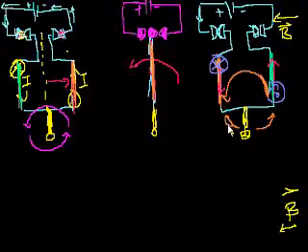I mean, most electric... Well, there's another way you could have done it. You didn't have to use the commutator. One methodology you could have used is you could have had the magnetic field going until you get to this point, and then you turn off the magnetic field, right? And maybe you wait for this situation to go all the way 180 degrees, and then you turn the magnetic field back on again, right? That's one possibility, but that's maybe not as efficient because half of the cycle you're not powering it. Or maybe you switch the direction of the magnetic field. Or another option, you don't have to use a commutator. Maybe you use some other contraption to switch the direction of a magnetic field.